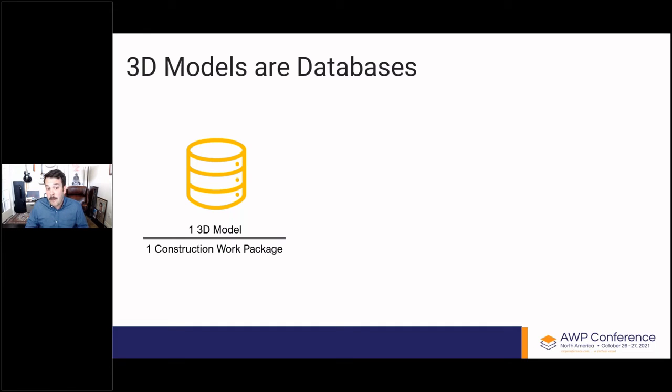But the best practice here is for engineering to deliver one model per CWP, and to deliver it in native format where possible. Typically it's a Navisworks format, which is fine, but deliver the DWGs, the DGNs, for Aveva it would be RVMs and attribute files. For Smart 3D it would be view files and MDB2 files, and for structural detailing it would be something like IFC files, which is Industry Foundation Classes. So it's a common structural detailing format. But deliver the native format where you can, so that downstream users can federate their own model. Again, it provides more flexibility with how these models are used downstream.